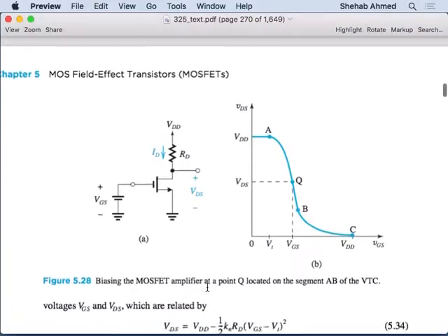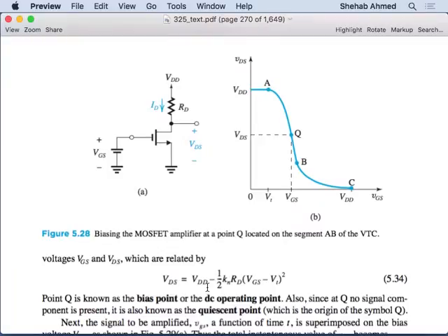Okay, so here is what we talked about, the idea of operating point. Here I don't have my small signal, I just have my large signal, my DC operating point. This is what we did last time. For a certain value of VGS, VDS, and VDD, we were able to find the operating point, which defines where VDS is, VGS is, and ID is, right? That's from yesterday's example, but here we put it on the voltage transfer characteristic instead of just solving for it and not knowing why that is useful, right?